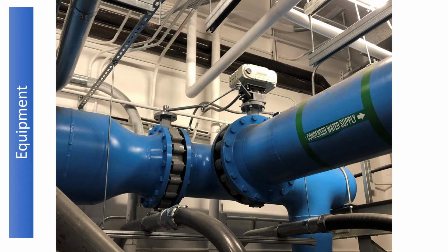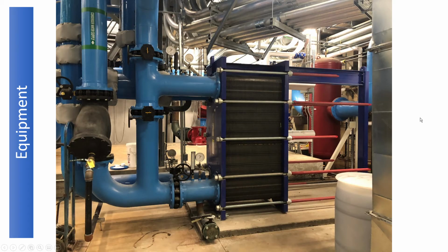But in certain cold conditions outside, a lot of times the cooling tower can make cold water, and we can simply exchange that cold water from the cooling tower and make chilled water out of that. And in those cases, this valve switches, sends condenser water through this pipe, and condenser water supply, that's a strainer, that's cleaning it up, into this heat exchanger.